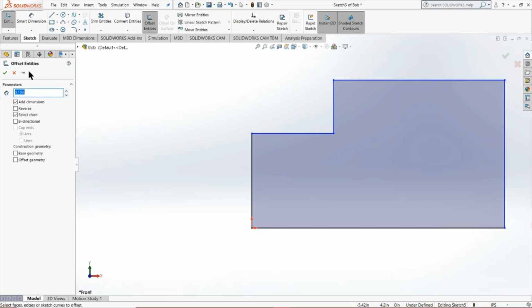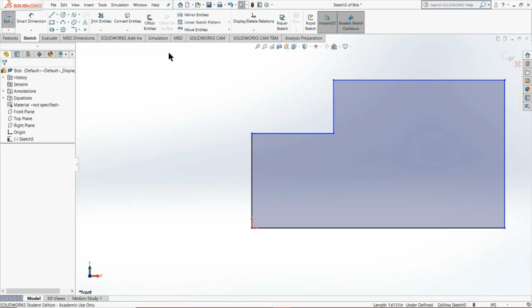So the Offset tool, as you can see by the picture, you'll already be able to guess what it does. If you click any type of profile, say we have our lines here, it creates an outline of what you had, and you can reverse the direction in any way you'd like. This is particularly useful if you want to make, let's say, a nut or a bolt. You could just make two circles that share the same midpoint, but have different radii. So that's particularly useful as well.